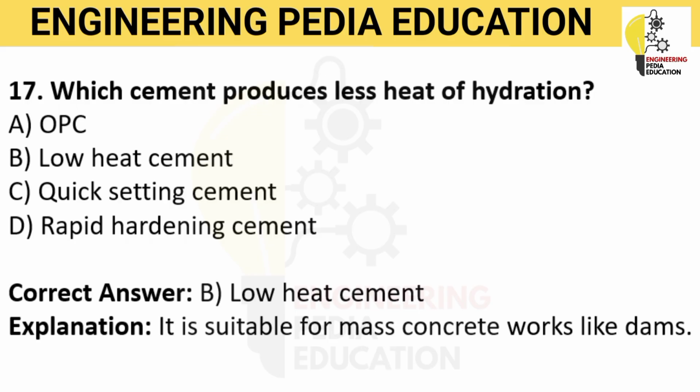Thus, in its composition, the percentage of C3S and C3A is lower, with a higher percentage of C2S. It is used in dams, large raft foundations, massive retaining walls, bridges, massive concrete work, etc.